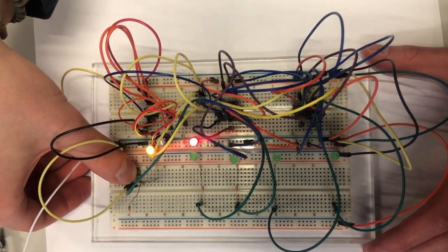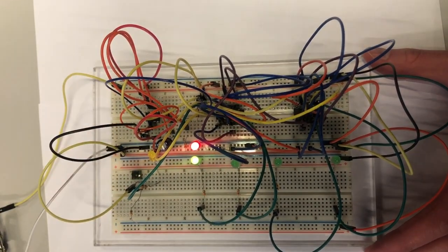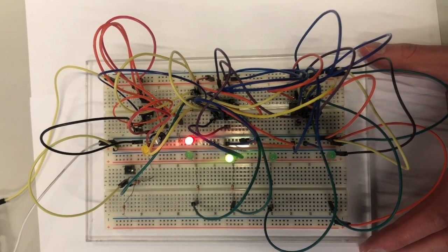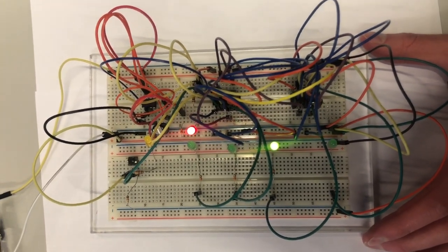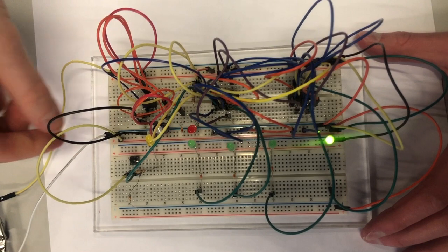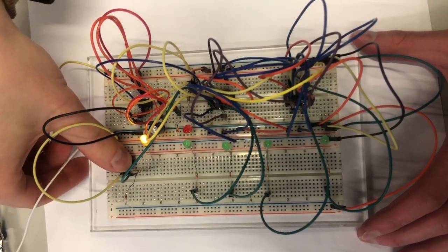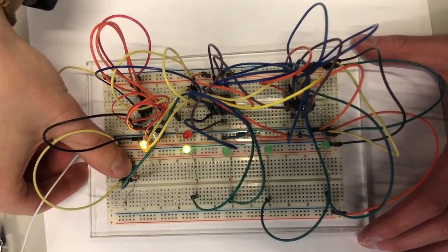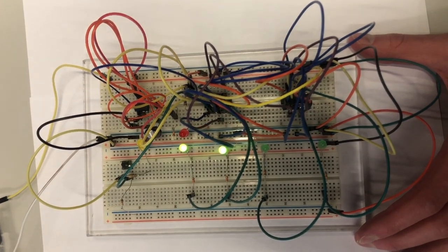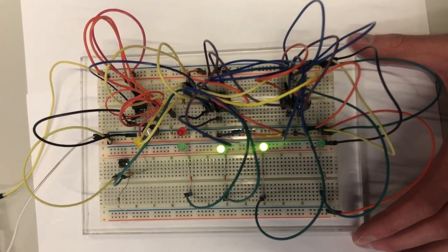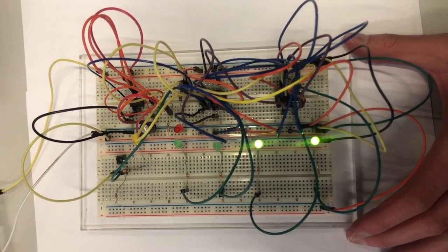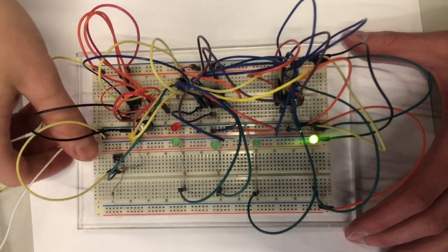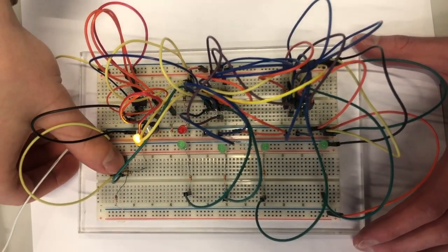But when we held the button down for 1 clock pulse, the shift register worked, so the first LED turned on, and then after that 1 LED at a time turned on after another. When we pushed the button for 2 clock pulses, both LED 1 and LED 2 turned on. After we stopped pushing, LED 1 turned off and LED 3 turned on, and then LED 2 turned off and